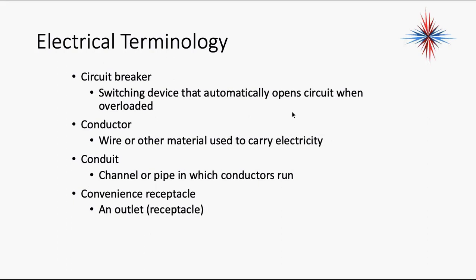The circuit breaker is extremely important. Every circuit has to have a circuit breaker on it. There's always a breaker panel someplace on these prints. And it's important to double check when you're installing equipment to make sure that the circuit breaker is adequate to handle the equipment.